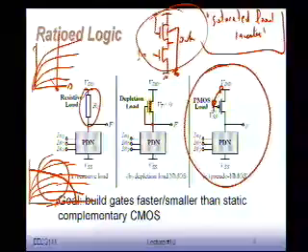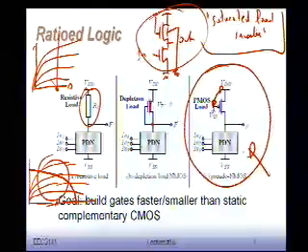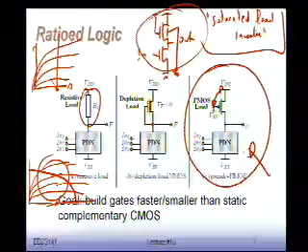So you actually get a lot of current out of this load device and get some decent performance. Of all the logic families in the ratioed logic space, this is probably the most popular one. We call it pseudo NMOS because the PMOS load acts kind of like the good old NMOS days. It's kind of nostalgia, trying to keep NMOS alive for a longer period of time.